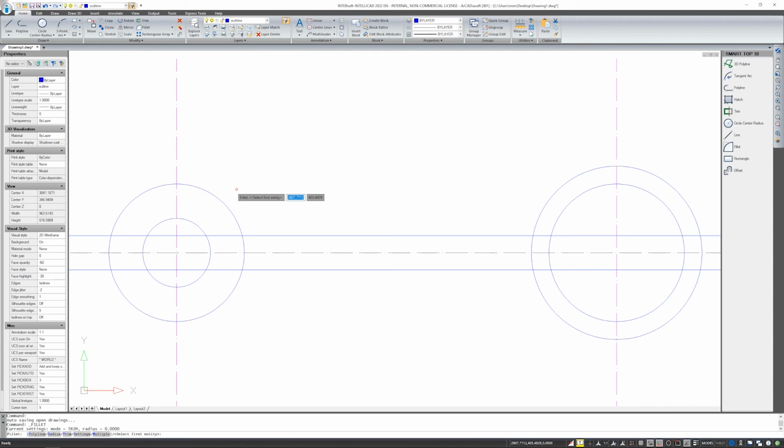It doesn't really matter what you choose first, whether we select an element and then choose the modification option or vice versa. I will show it interchangeably here. When I round something off, I turn on the Fillet option first and then show the element. But mostly I select the element first and then I choose the modification option with the right mouse button.